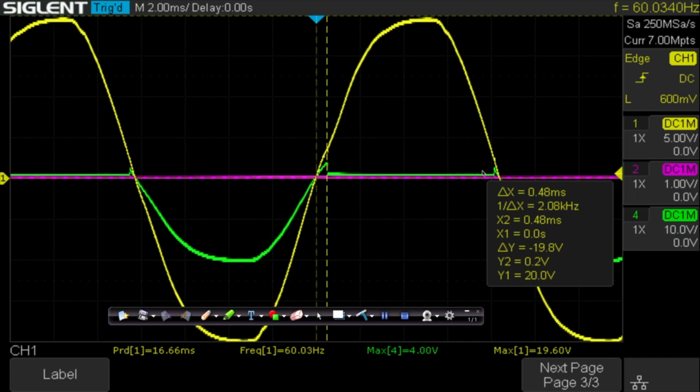In that case, the big area in the center here is the conduction angle. So if you take 180 degrees minus that, it's 169.62 degrees. That's the conduction angle, and this time we're firing as early in the cycle as possible, so the SCR is conducting as long as possible. If you were to put your meter across the load, you would find that's the highest average load voltage.